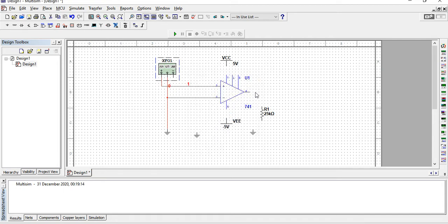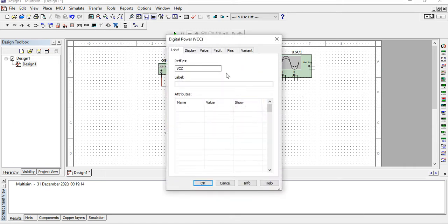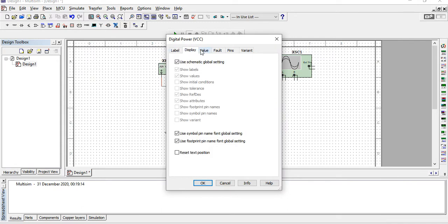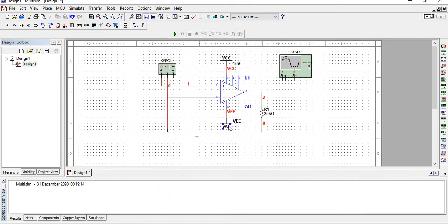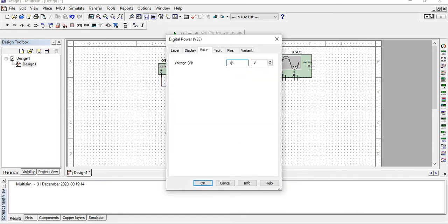And finally we will observe this on an oscilloscope, and make a connection here and ground it, right? This goes with your 4 and this is with your 7. Mostly when you are reading theory, these supplies are not mentioned, but these are mostly used. It's a 15 and it's a minus 15.